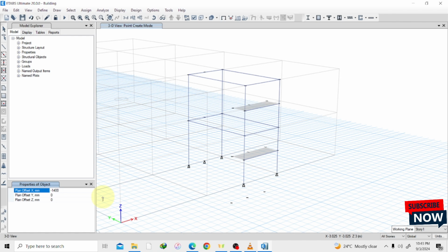1500. So, okay. And I just select this joint. So I have this joint here and also another point here, and I also do the same for here. It's in all stories, so whatever I do here also replicates here. So now I have all my points to be able to draw my incline slab, because we know that our staircase too is a slab too.